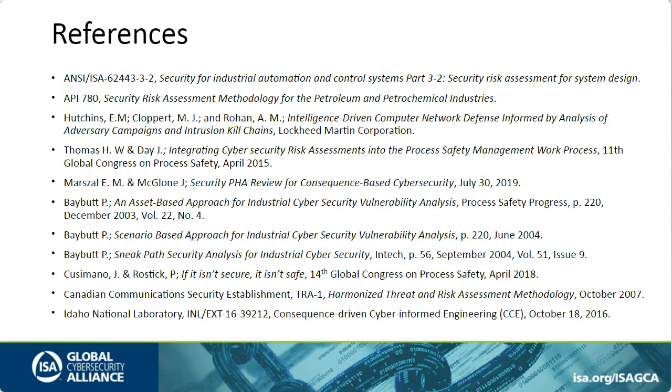Next question from the audience. Can you elaborate on defense in depth? Yeah, as I said, when people throw that term defense in depth out a lot, a lot of people seem to think that it's simply putting a firewall between each level in the Purdue diagram, and that couldn't be further from the truth.